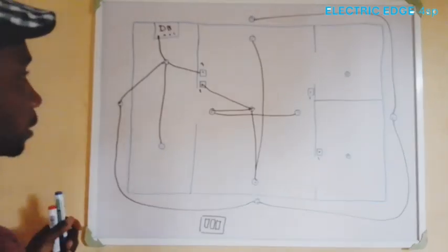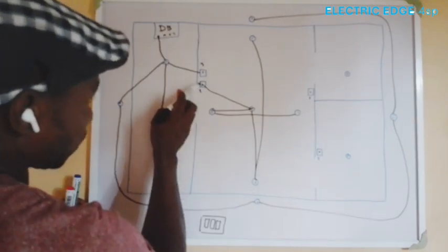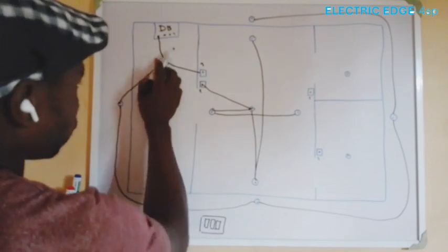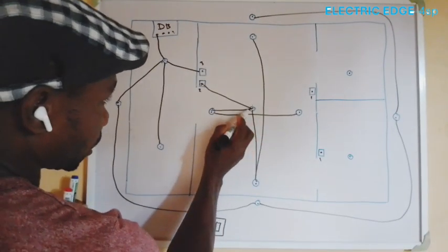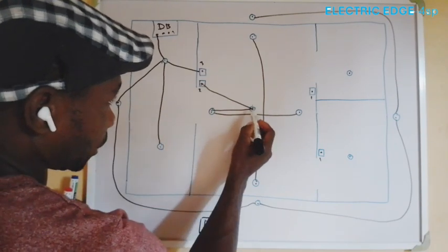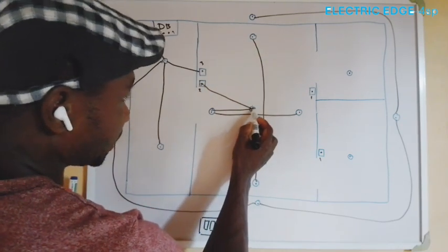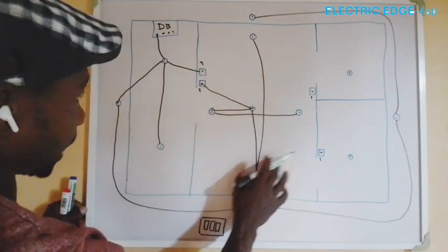But in most cases, it doesn't matter, because when you pass your wire from the switch to this box, what you are trying to do is that, for instance, if this is a 4-way box, this one is going to the switch, this other one is coming here, the third one is coming to this to link this, then the fourth one will send the mains to the next switch, so that you continue with this circuit.